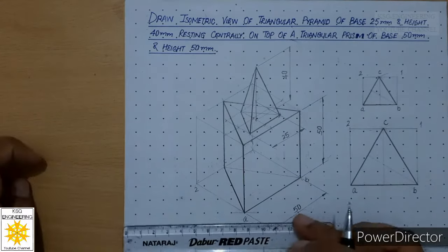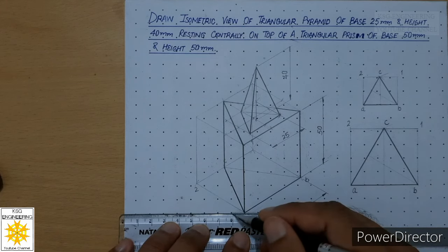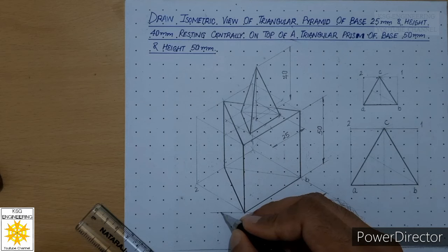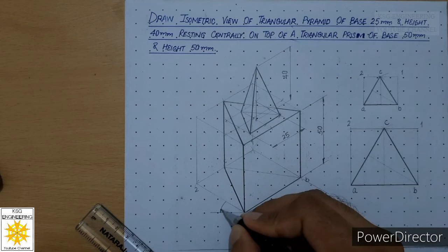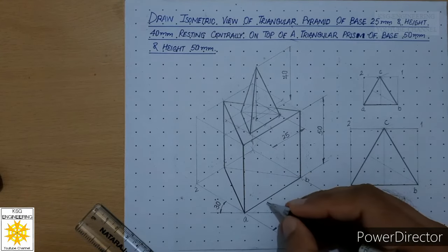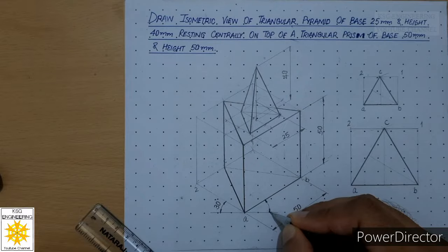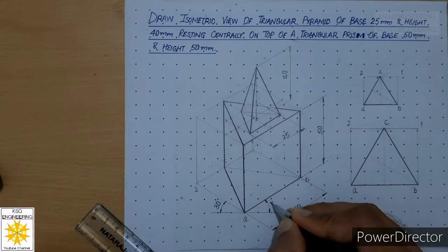After that, we will place angles at the bottom. So for that, we need to extend this line on both sides. So add a curved dimension line, closed filled arrowheads on both sides, and in Gothic style we will write 30 degrees. Similarly on the other side, curved dimension line, closed filled arrowheads on both sides. So we'll write over here 30 degrees in Gothic style.